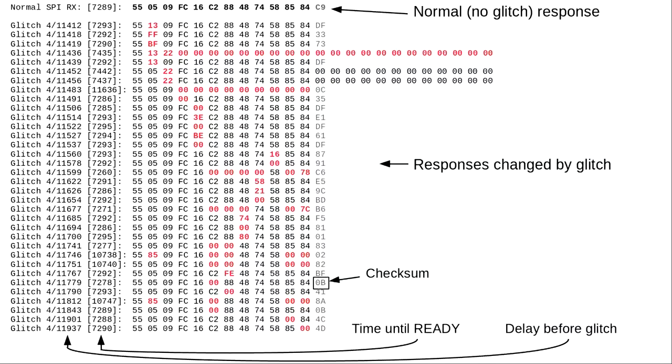To test the glitcher to find out if it will work and what voltage levels are successful, we can send a command to the ACP, then glitch, and then see the response from the ACP. The general strategy is to lower the voltage just to the point where the chip sometimes resets due to the glitch. By adjusting voltage levels and glitch length and timing when the glitch will land, I succeeded to cause ACP responses to be altered. The checksum on SPI packets is very convenient. When unusual data is received from the ACP chip with a valid checksum, it's a pretty good sign that the glitch caused a temporary fault within the CPU, but that normal operation was resumed.